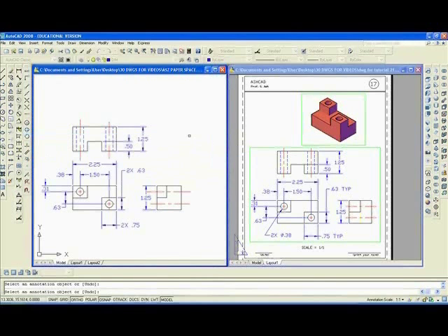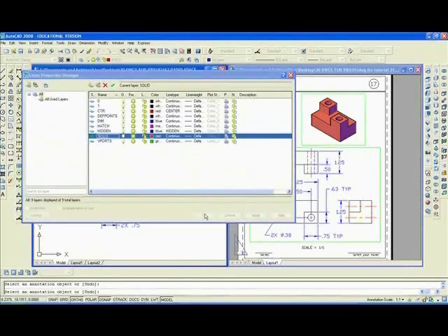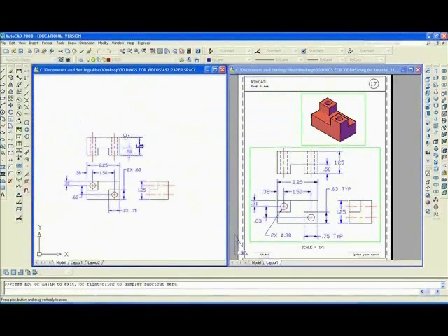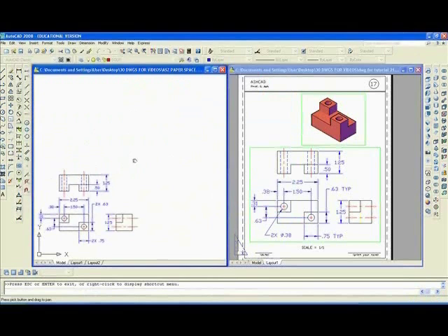Okay, so the drawings are complete, and now I can go on to making a solid. What we'll do is to change the layer, make solid current, zoom real time to shrink it down in size a bit, then pan, put over in the low left.